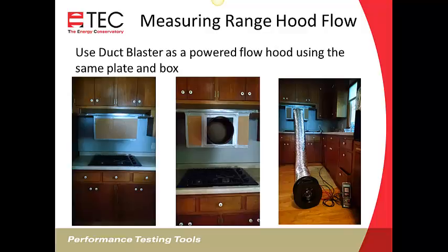So we turn the kitchen fan on, and this whole device we've attached is going to create some resistance, right? The kitchen fan is going to make the pressure in that box more negative, because it's trying to move that same amount of air that it did at free air. So when we get to our DG700, the kitchen fan is running, we turn on the DG700, we're going to see a negative pressure in that box, because this has created some resistance on the airflow.